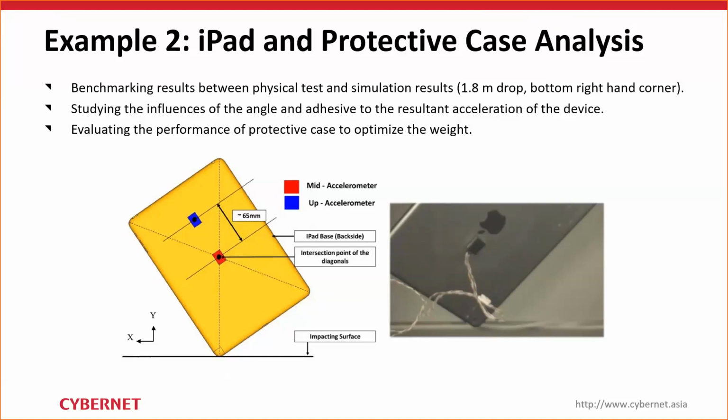So in this particular case, we put it at those two particular points. And then inside Ansys as well, we can choose those very specific points to measure the resultant acceleration. Therefore, we eliminate the accelerometer position variable, making it easier to compare between physical tests and simulation results.